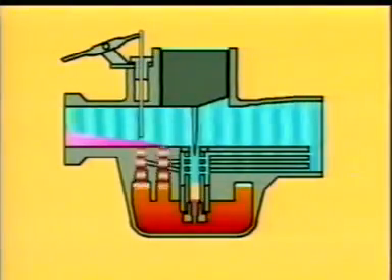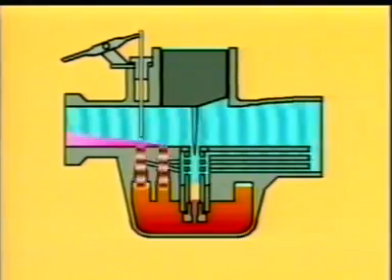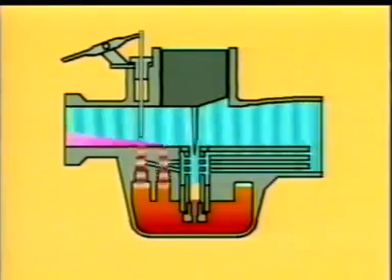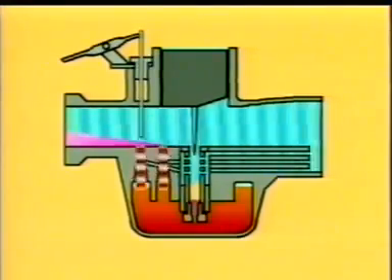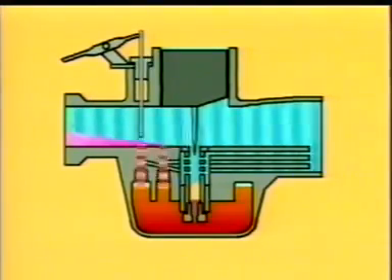This is because opening the throttle valve sharply reduces the amount of negative pressure generated by the engine, which results in less fuel being dispensed. It also allows a larger volume of air to be taken in, causing the fuel-air mixture to be leaner.